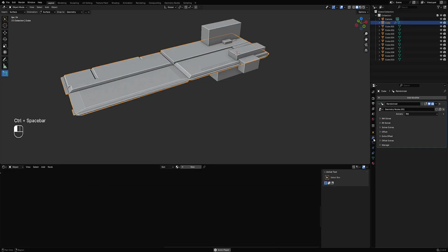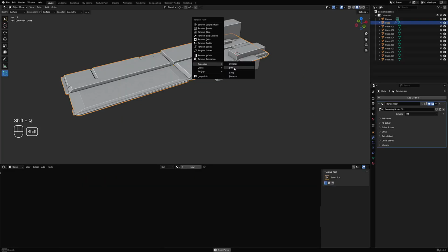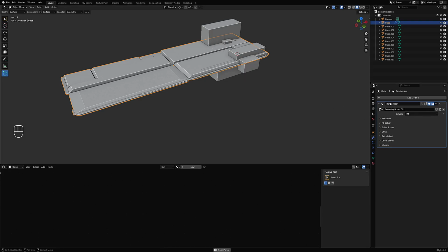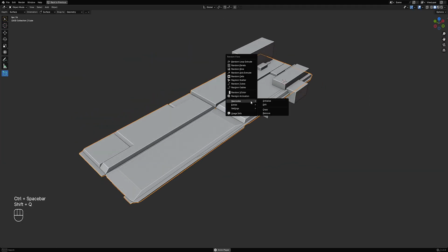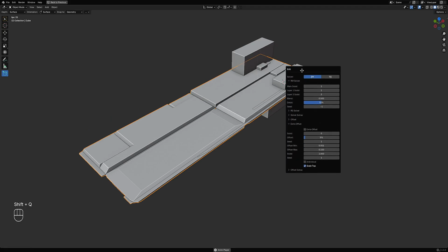You can just use the edit command in the geonode features submenu or edit it using the modifier. This reflects what is in the modifier, and what you do here will also be taken to the modifier as the new settings.